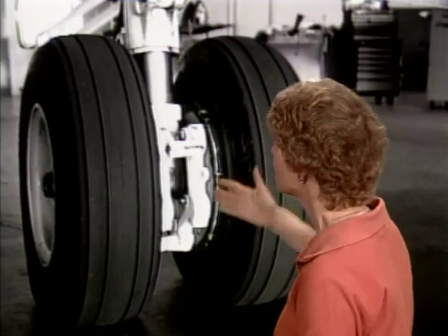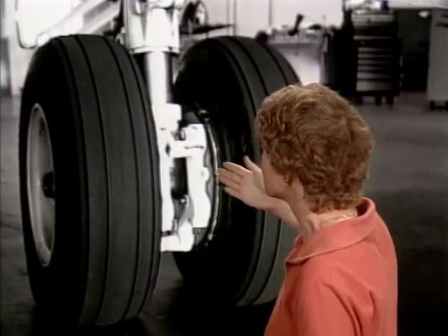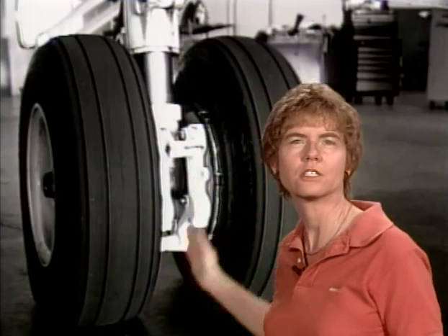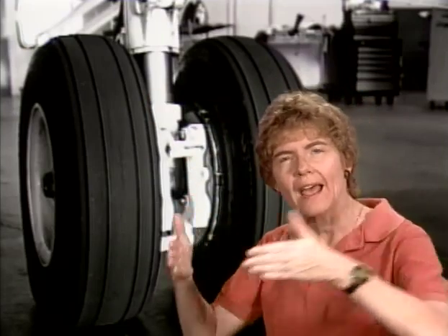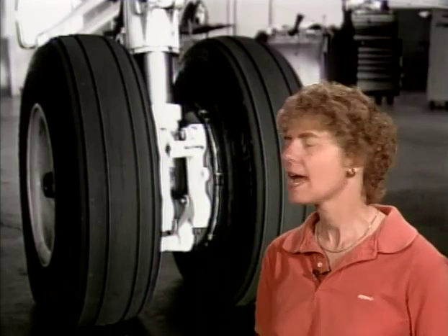Now, when you're looking at the landing gear on an aircraft, you want to make sure that you don't have toe in or toe out. So, what is toe in and toe out? If you took the longitudinal axis, meaning the front to back axis, on the main landing gear wheel assemblies, one on each side, and if you extended them, if they met aft of the aircraft, on the rear of the aircraft, that would mean that the wheels have toe out.